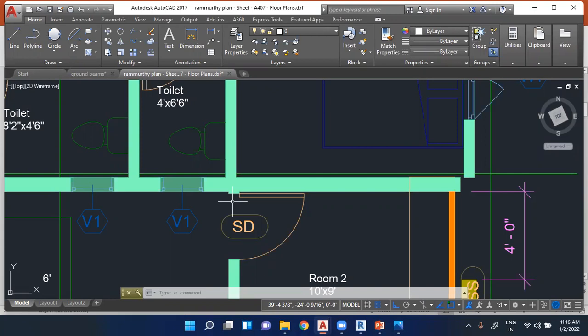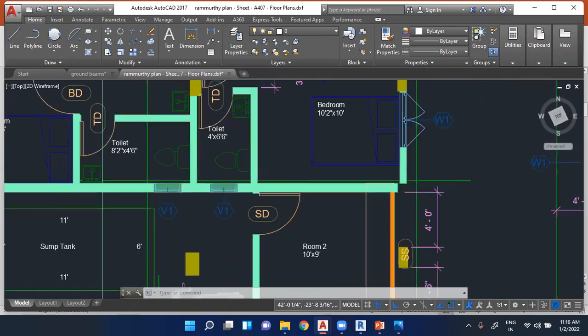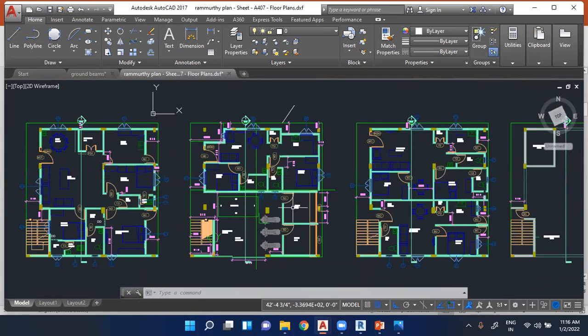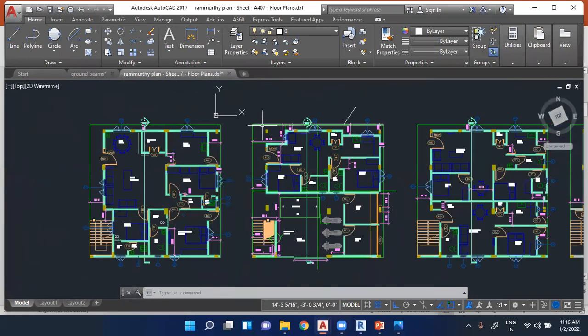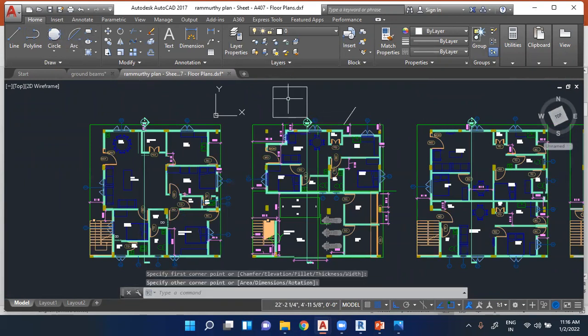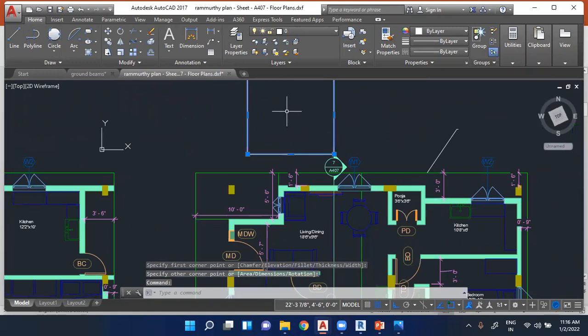And we can apply point clouds in which we can easily see the 3D models in a 2D fashion, and the calculation of mass, area, volume, center of gravity in no time. Because when I'm selecting this, when I have a rectangle or whatever area I have, it'll give me the center of it, and it will calculate the area which this polyline or rectangle is encompassing. These all features make AutoCAD a very useful tool for drafters and designers.